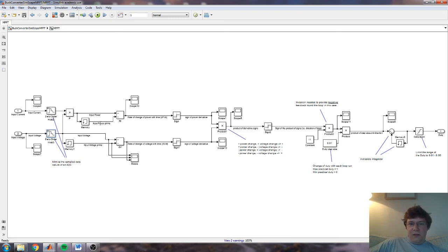The fact that the amount of time it takes in each step changes according to how much the equations are non-linear or unwilling to come to a consistent, self-consistent solution, is neither here nor there. The fact is there are steps, so we can do the whole thing digitally. But if you're doing this in, I don't know, a Cortex M3 or something, you would also be in a digital system by this point anyway. And in fact the zero order holds here